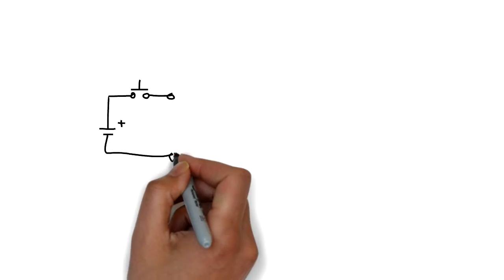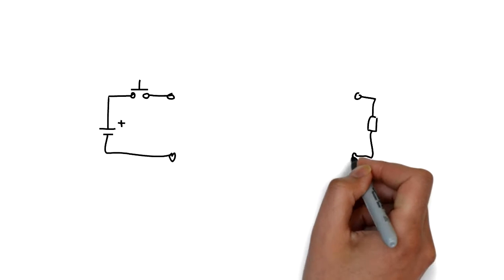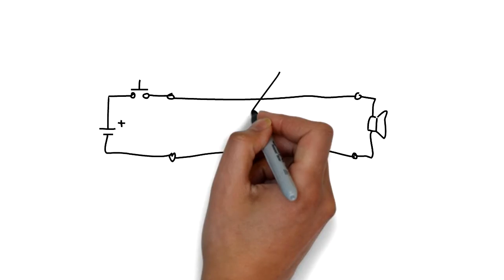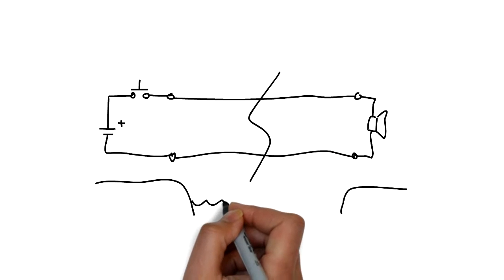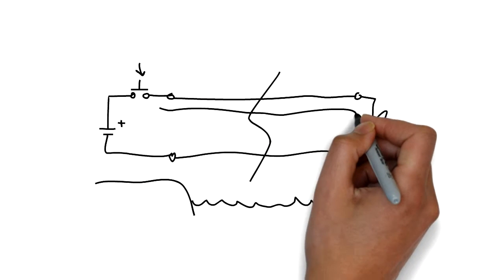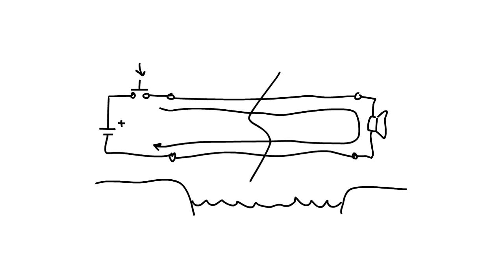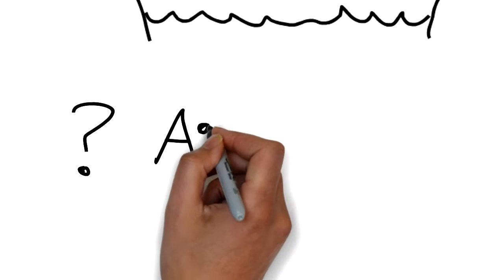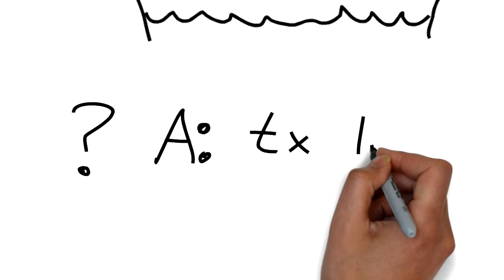If we make a telegraph circuit with a switch on one end and a beeper on the other and send it a long distance, let's say across the ocean, when we close the switch, does the beeper start immediately? If we're just passing a current around from one side of the ocean to the other, it'll actually take several minutes for the beeper to turn on, and it would turn on really slowly as the current starts to build against the inductance of the line. So how do we get a signal across the ocean at a much faster speed? We use a transmission line.